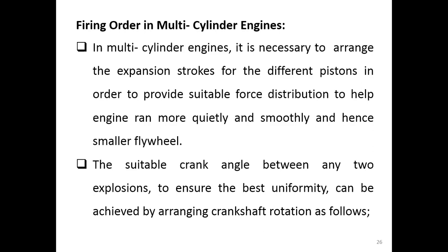The reason is that we need to arrange the expansion stroke for the different pistons in the cylinders, so that when combustion happens in each cylinder, it can provide a suitable force distribution to help the engine run more quietly and smoothly.